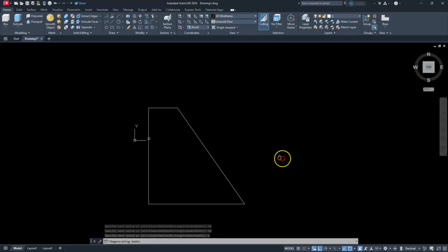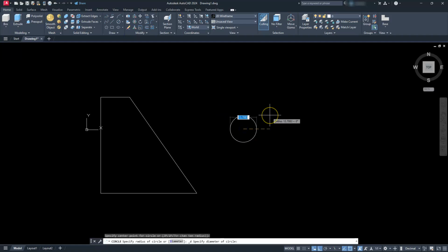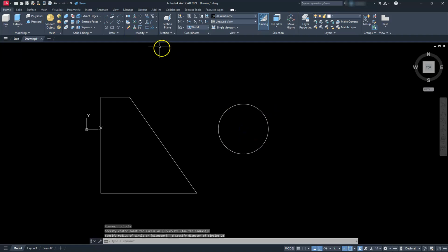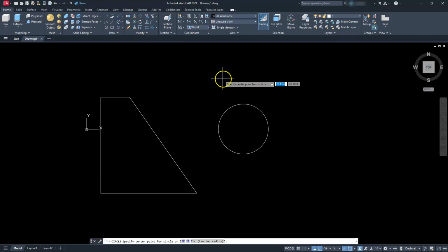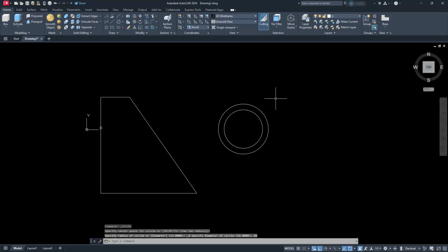The next couple of shapes I'm going to create is going to be that pipe. So all I'm going to do is create a circle with a center diameter, right? So the circle command is located here, center diameter. Let's go ahead and click here, give one of them 26, go back to the circle center diameter, and then I'm going to place it at this center. You remember I always like to give a little preview of it, and then type in 20. All right, so that's what's going to represent each one of those two pipes that I need to create.